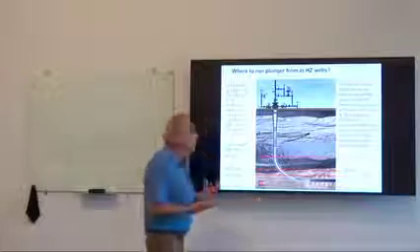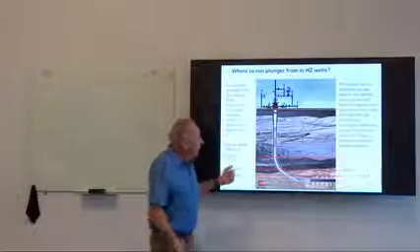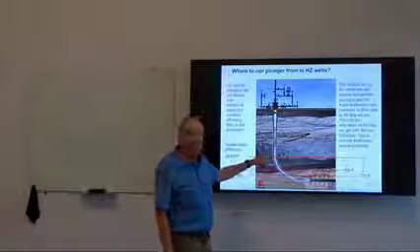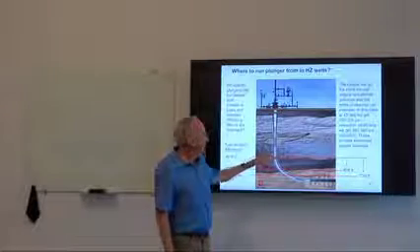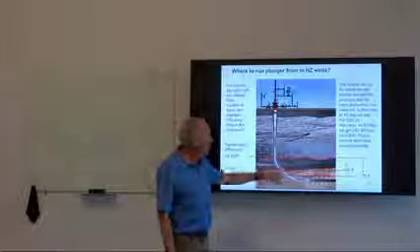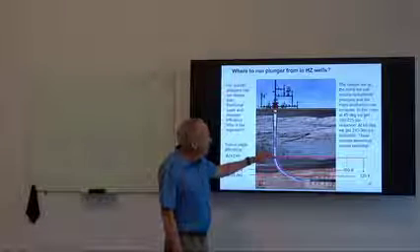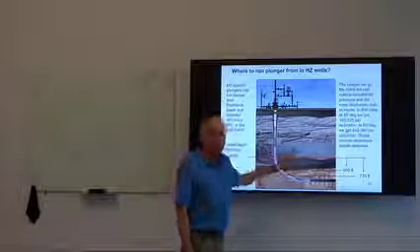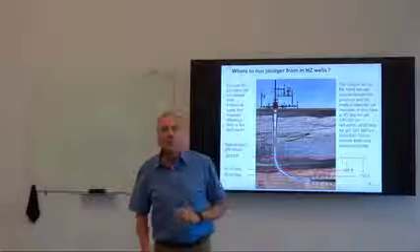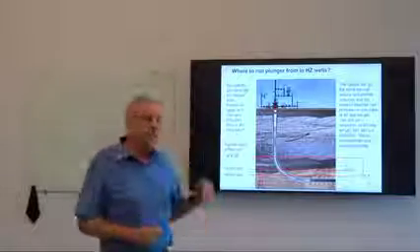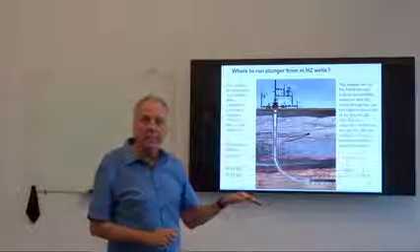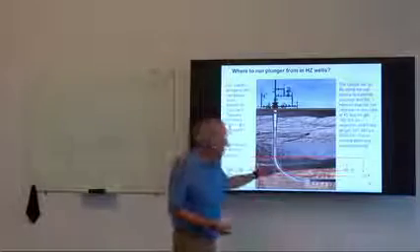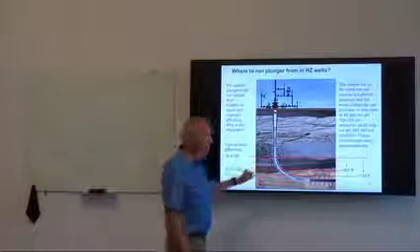It has some meaning. So, for example, if we were to think about pumping or setting our bottom hole assembly at a kickoff point on this horizontal well, we are perhaps missing out on an opportunity to reduce the height of the fluid column in TVD terms by coming down and setting our tubing and our BHA at lower points.